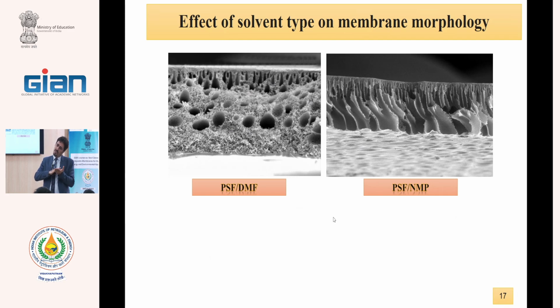In this case, we use a sealing agent for filling the cracks. For ceramic membranes, for sealing, we use very fine powder. When we have big pores and big defects, using a thin layer of very fine powder as a top layer, we seal these cracks. This is mostly named a protective layer.